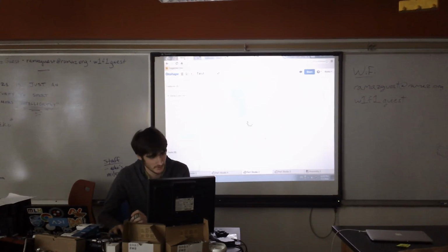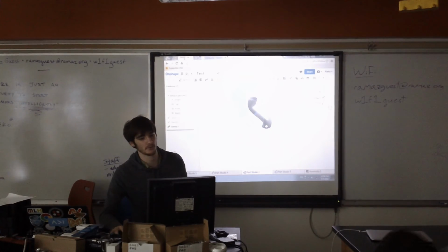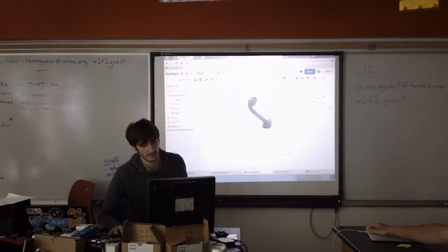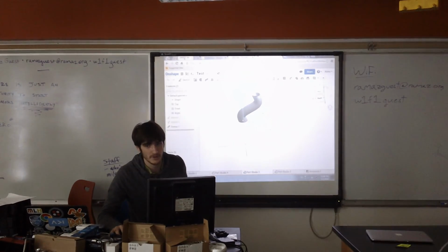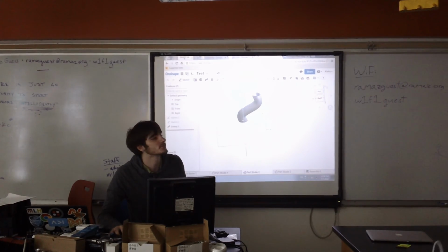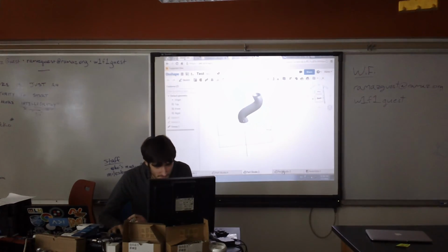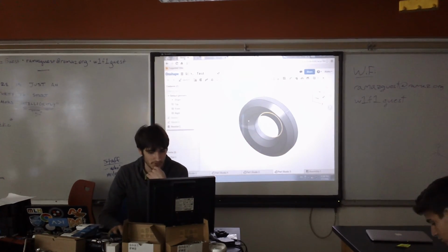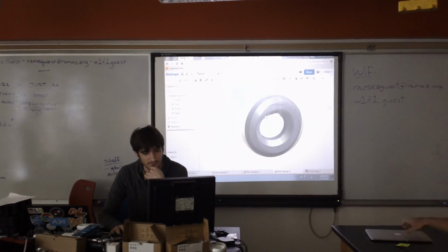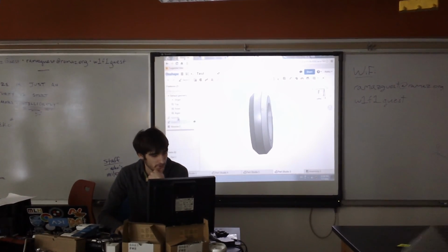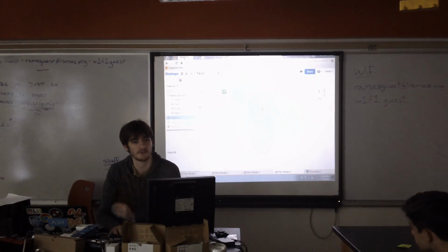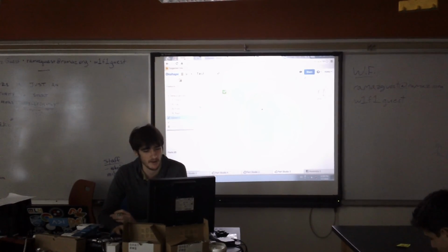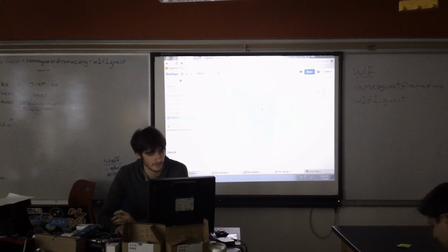All right, some other cool things you can do with this. You're just going to have to really play around with any CAD software to get a feel. So this was done with what tool, do you think? Sweep. Any other ideas? Everybody thinks sweep? Good. That was done with the sweep. What about this one? Right, that's revolution. And if we edit this, you could quickly change the cross-sectional shape. You could make it a circle, a square, whatever you want.